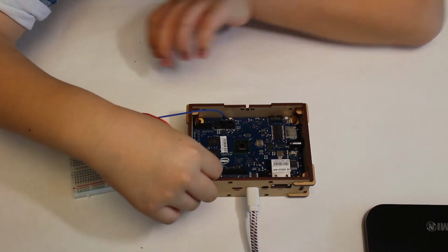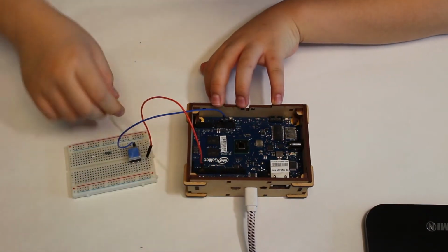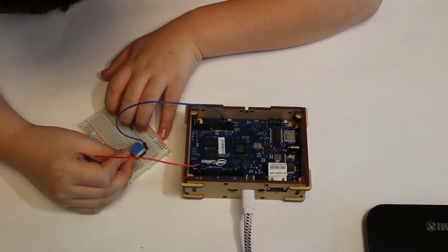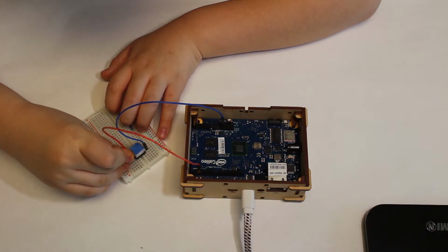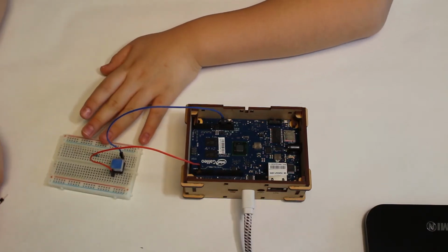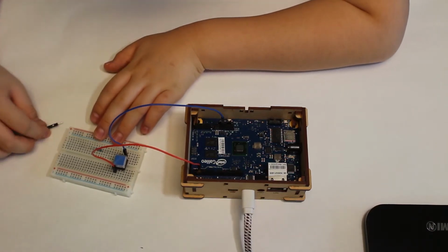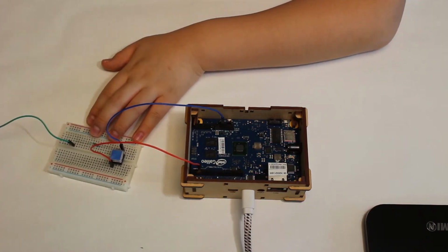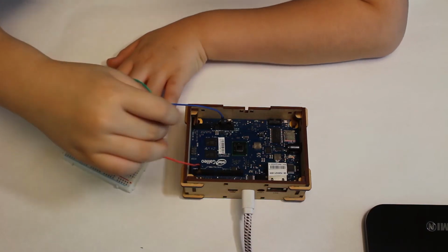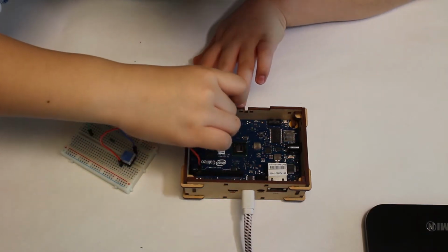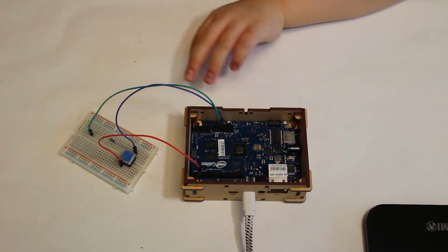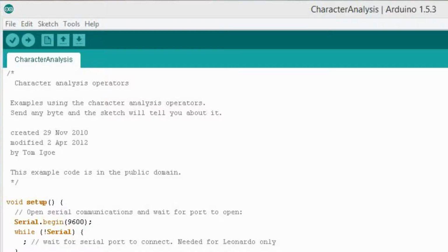The 1K ohm resistor used in this lab is called a pull-down resistor. It may seem like it becomes high when you press the push button and low when you take it off without a pull-down resistor. However, actually, without the pull-down resistor, it becomes very unstable. We call this state floating and you must avoid it.